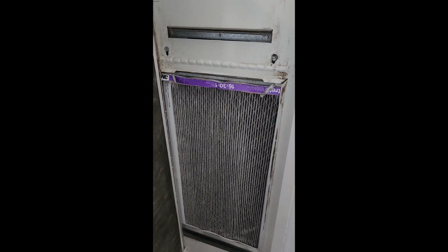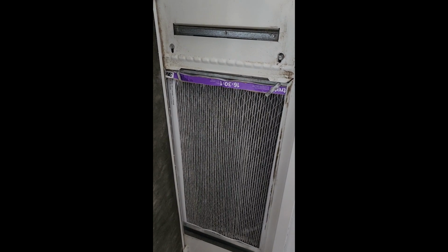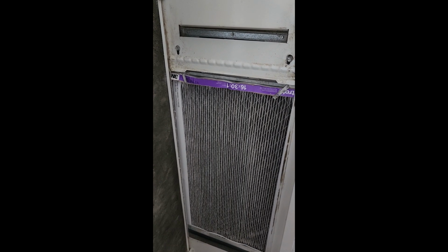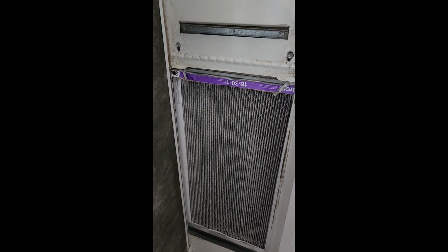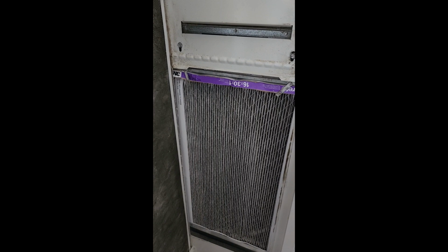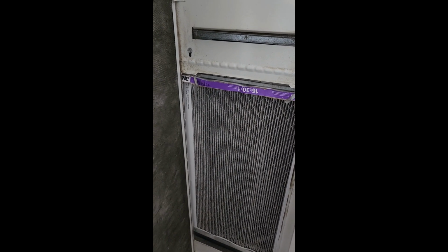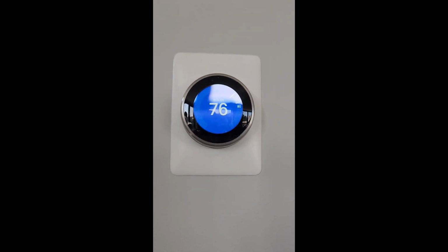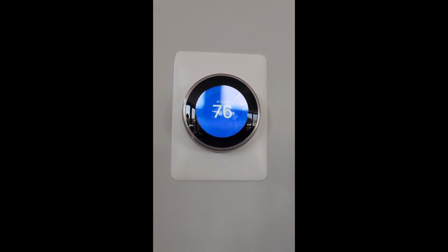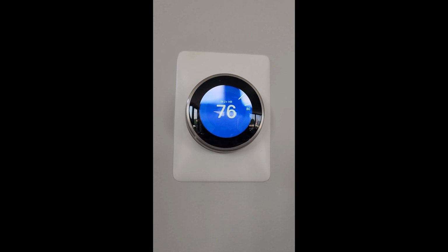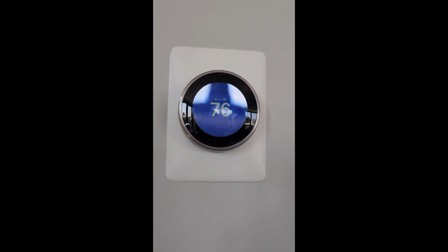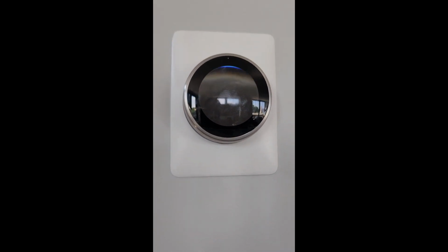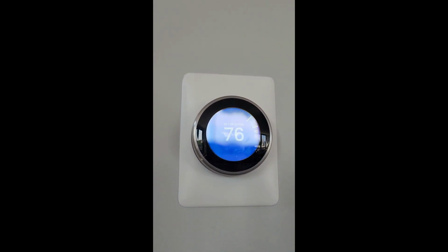One of those would be an electrical problem. If there was an electrical problem, we would not be hearing the compressor. And that is pretty much something that we can avoid having to even waste time on checking. Now, here is what we know. We know that we have good power going to both the thermostat and to the HVAC unit itself because the thermostat signals the compressor to turn on. We hear the compressor turning on, but we do not actually feel any cold air.